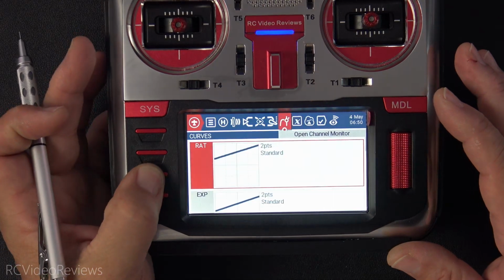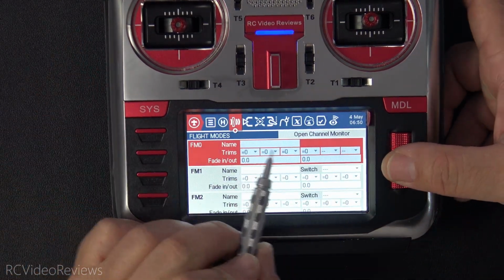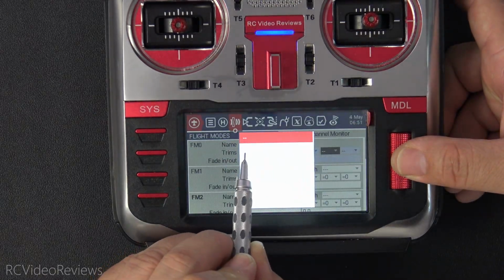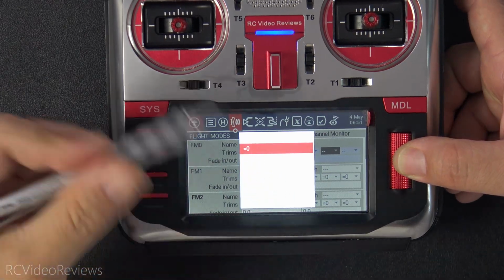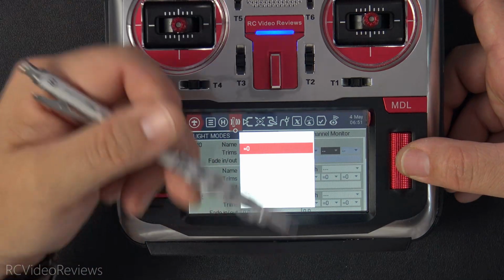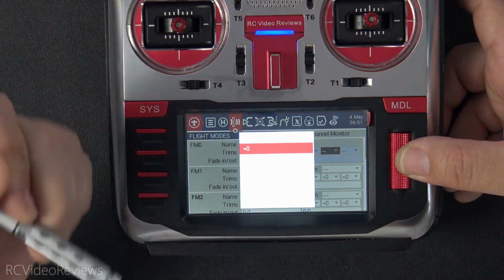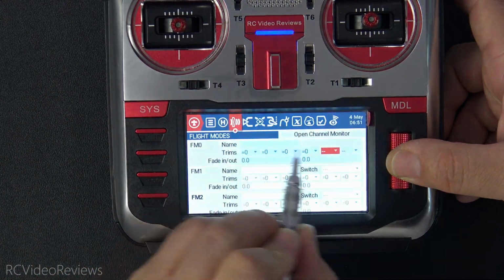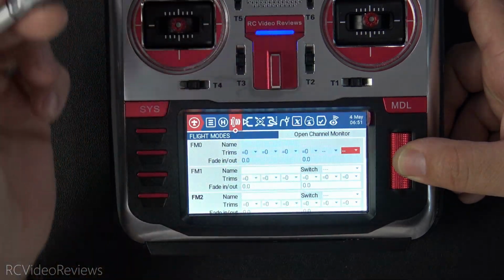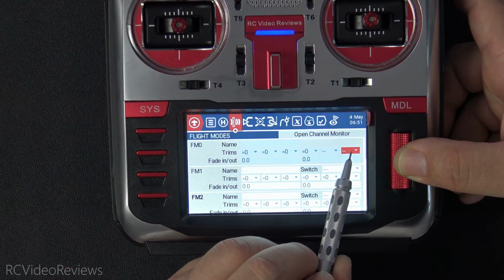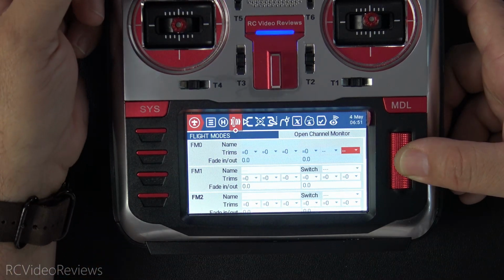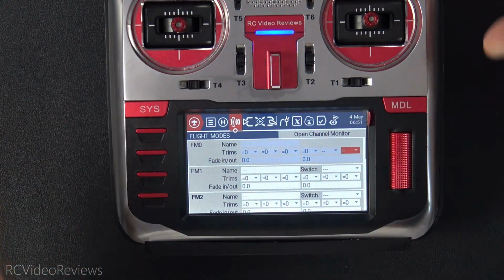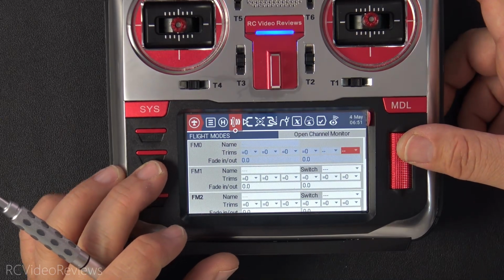Now, there's another thing you need to do if you want to invoke this 5 up and down trick to play the values. And that's you want to go into flight modes and turn off number 5 and 6 as a trim option. So the reason you do that is because if you don't turn this off, it'll default to equal 0. Every time you press that button, you'll hear a beep. And then eventually, if you keep pressing up, it'll say trim maximum reached. And we don't want to do that. So you simply disable T5 as a trim switch by putting a dash right here. And while I'm at it, I also do T6 in case I want to use it for something else. So T5 and T6 are now disabled as trim switches. That means I can now utilize them as momentary switches in my configuration. And they won't beep, and they're not subject to trim maximum reached. That's why we do that.